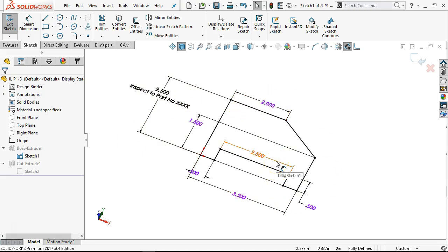So my logic, the way that I prefer to operate, these are irrelevant because when I'm pulling this out of my imagination, I'm dimensioning to what's convenient to create the part. I'm looking into the future as to when I create the detail, what's going to be important to me. When I create that working document to go to the manufacturer, then I'm detailing for the manufacturer, and this would be an important note for me to include. All right, the rest of these, not so much. So I can exclude them and then include just the ones that I place a higher priority on.